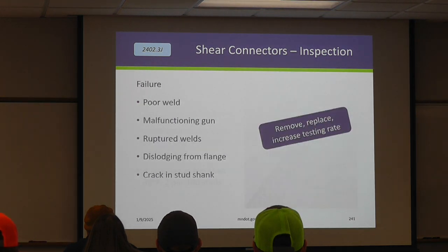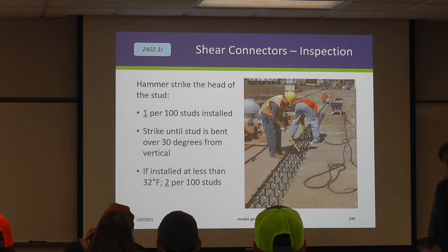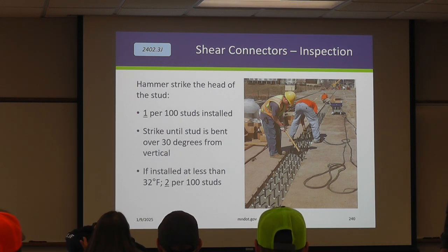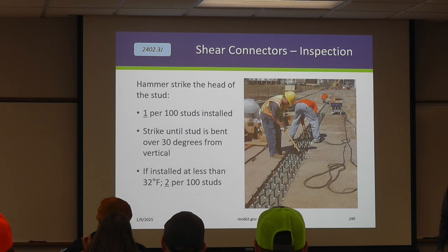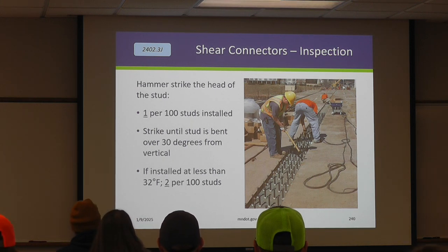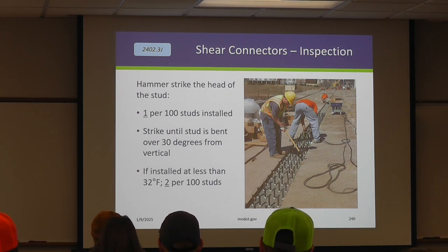So I see it says here in the spec that it's after the weld cools, so on a normal summer day, how long would that typically take? This is a really small weld. I know, but it's really thick. Really hot too. Couple minutes. It really doesn't take that long. It's a trade-off because you want them to be far enough ahead of you, but then you don't want them to be too far in case you find a whole bunch of problems. But it generally doesn't take that long. Yeah, I'd say 5 minutes is probably the longest you're ever going to have.